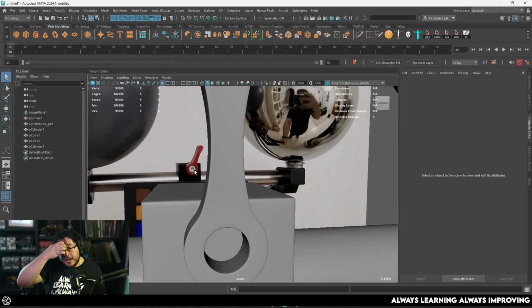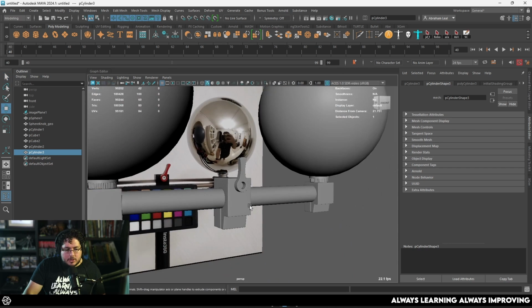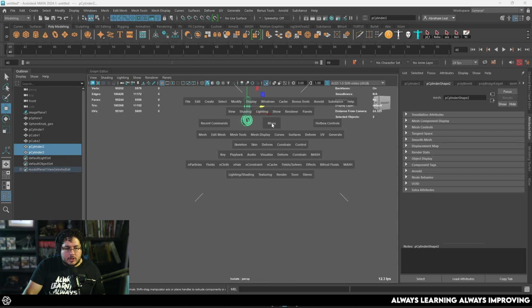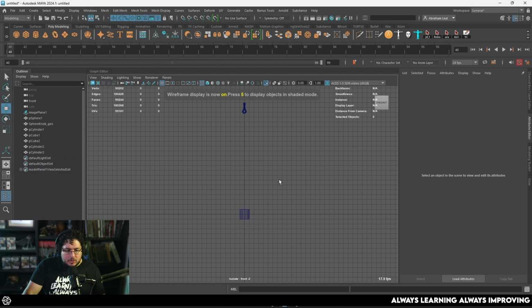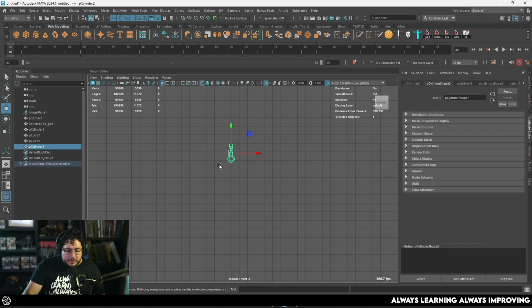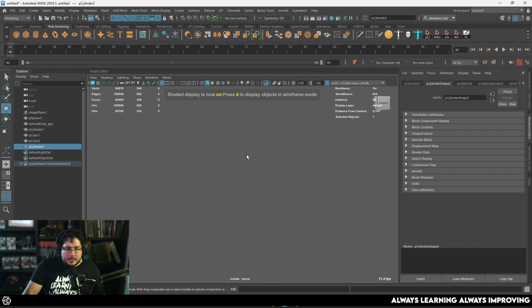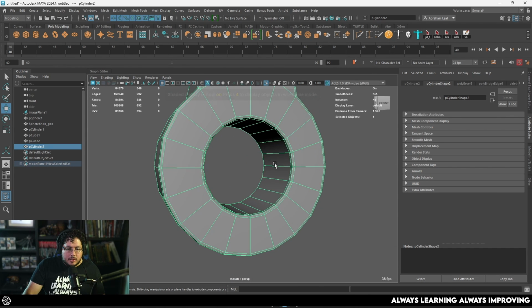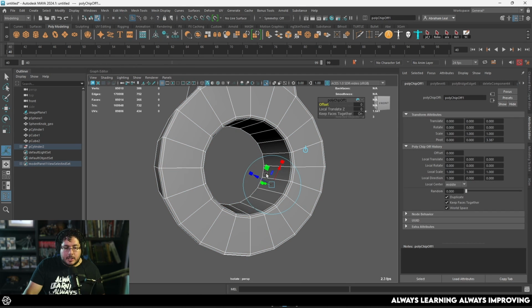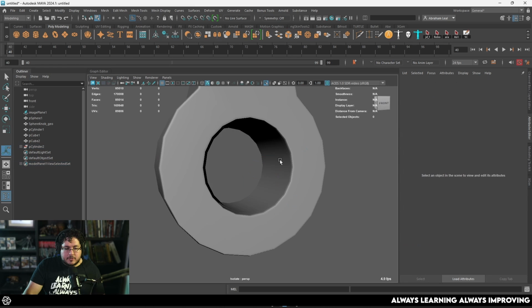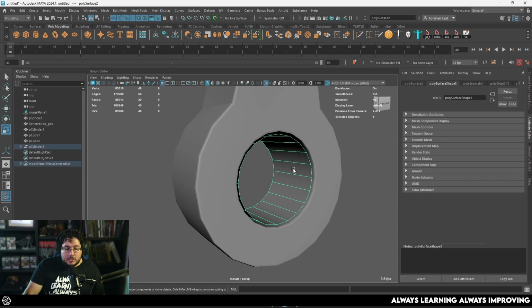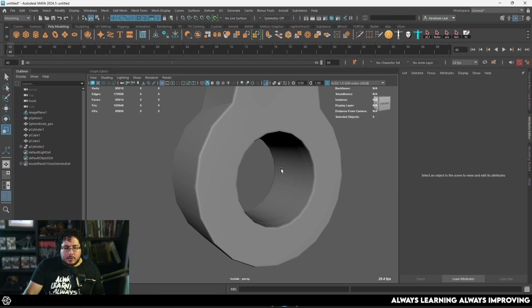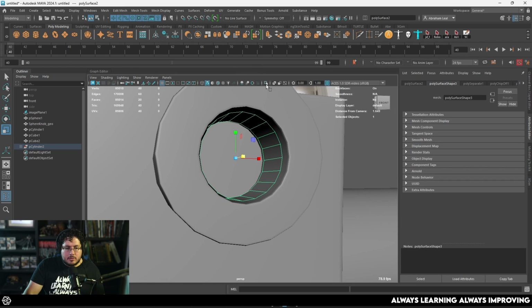And then we've got a hexagonal sort of bolt, right? So I'm going to grab another cylinder. Let's isolate both of these guys. Actually, now let me show you another trick here. I'm going to go to this guy right here. And since we already have the faces, I can just grab these faces right here and do an edit mesh and a duplicate. We just duplicate the faces from within this object. So I know that this is exactly where it needs to be, and it's going to be the proper size and everything. Now this one right here, let's isolate.